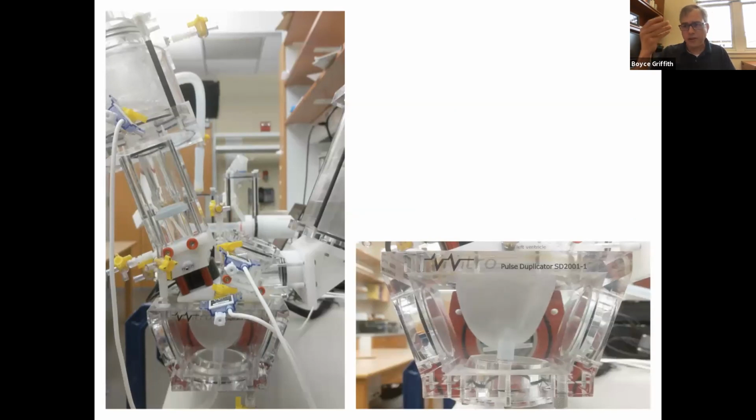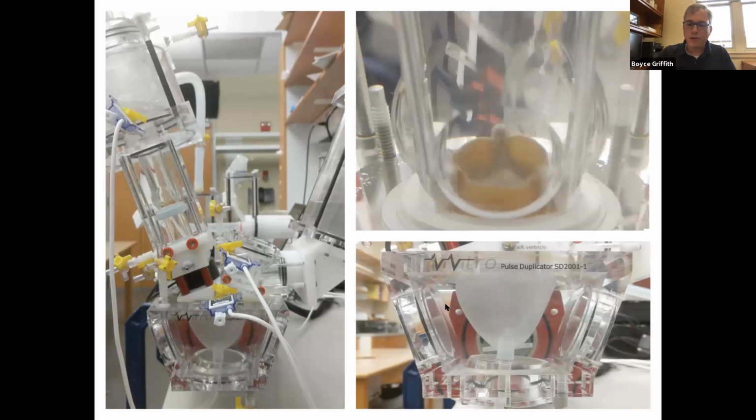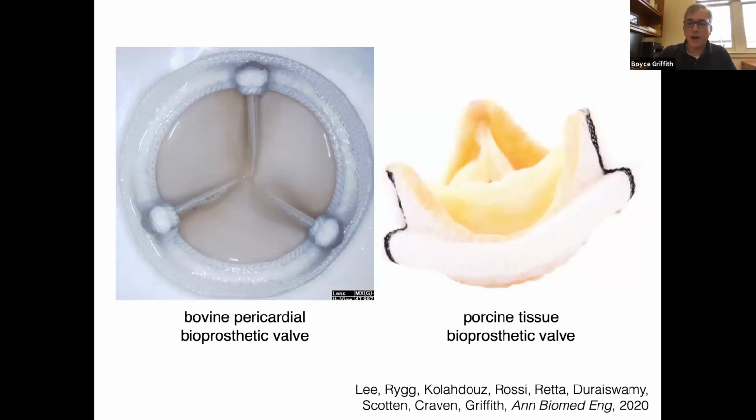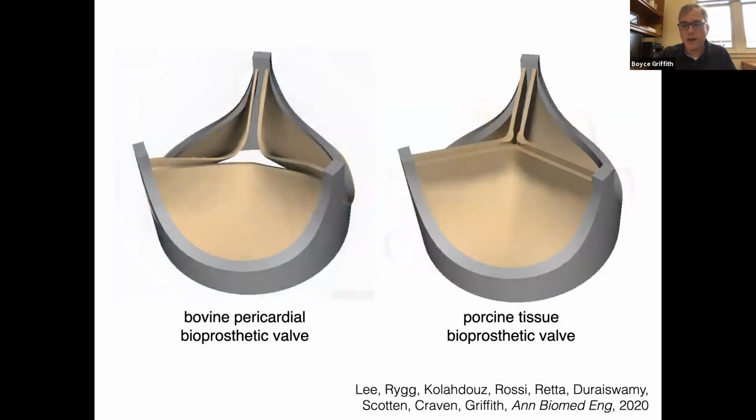The bag is modulated by a programmable piston pump. The way that this works, there's water outside of the bag, and then there's a test fluid inside of the bag that is in this contiguous flow circuit. The test fluid is typically saline or glycerol solution. A nice thing about this particular setup is that you can interrogate the flow fields using techniques like particle image velocimetry.